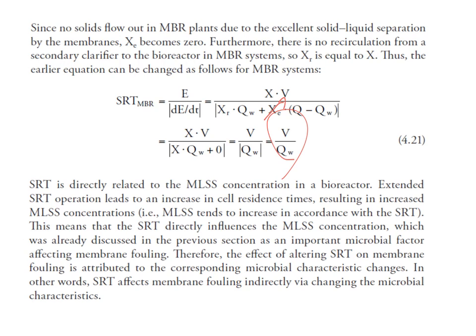so we can just have a very simple equation. So SRT is directly related to the MLSS concentration in a bioreactor. So extended SRT operation leads to an increase in cell residence time, resulting in increased MLSS concentration.